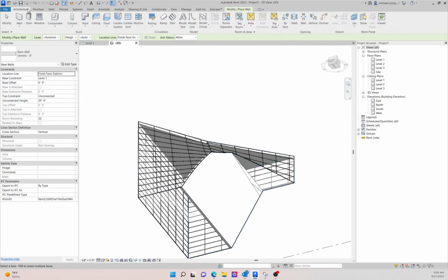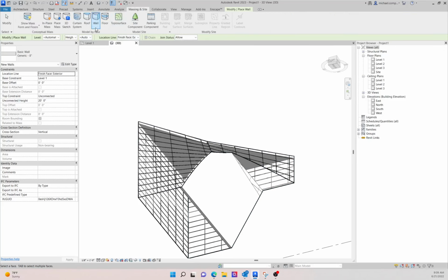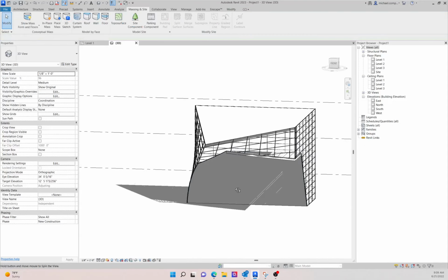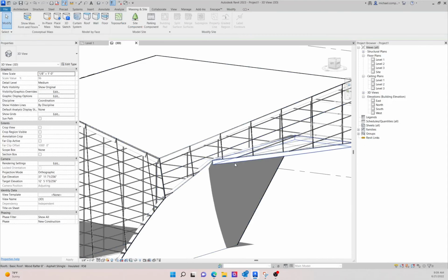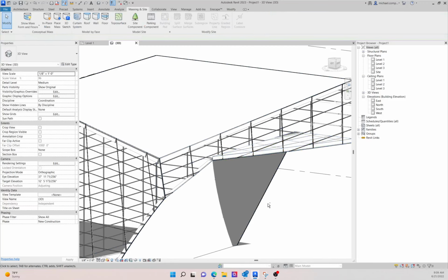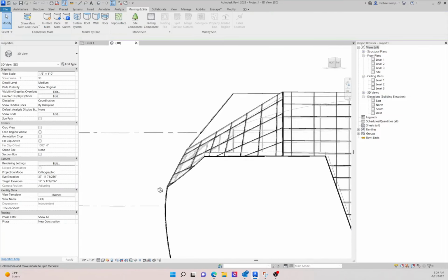So typically that would be a ceiling. So we're going to see if it will let me do a roof instead of a ceiling. And see, yep, there we go. Now, obviously, we don't want that hanging down the way it is. So we would probably manipulate that by the thickness, to offset it by 8 inches. And that way it's tucked up in behind the curtain system.